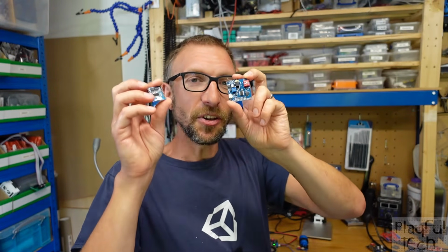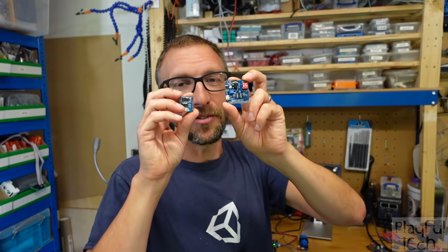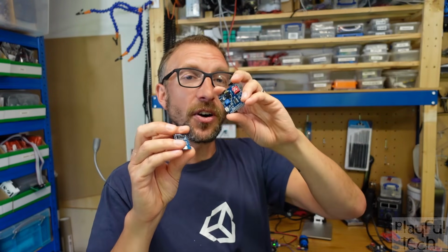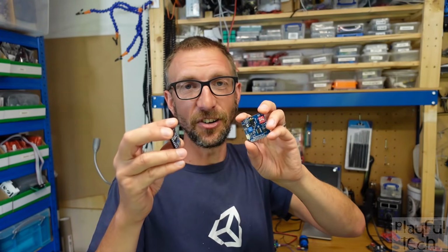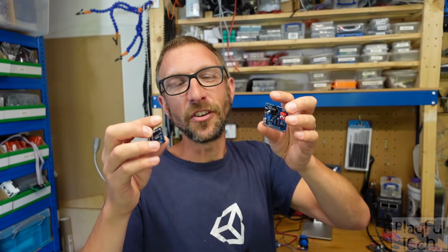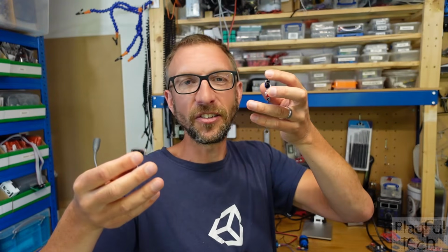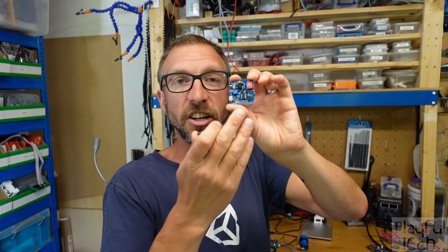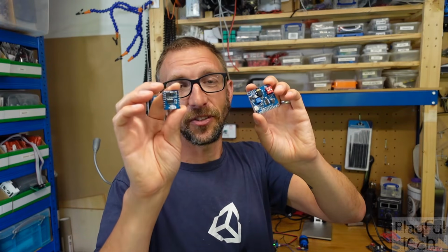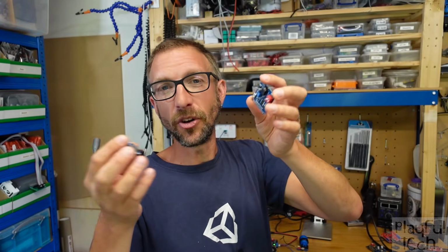Now the difference between the 8F and the 5W boards is that the 8F has a flash memory chip, like the SV17F did, while the 5W has an SD card slot, like the DF Player Mini. So when you come to choose between those 2 units, the obvious decisions are things like speed of access versus storage capacity. This is actually an upgraded amount of flash memory, so it's 8 megabytes on here, twice that of the SV17F, and that's sufficient to hold a couple of minutes of high quality MP3 data.